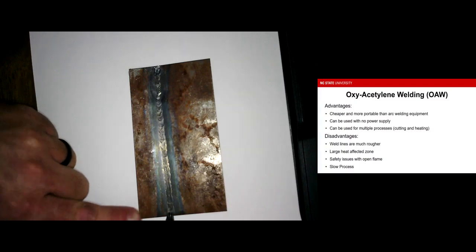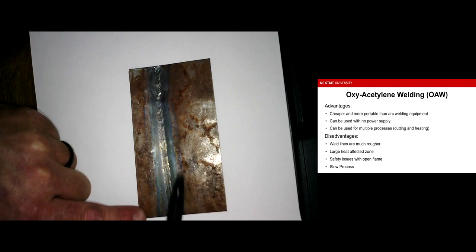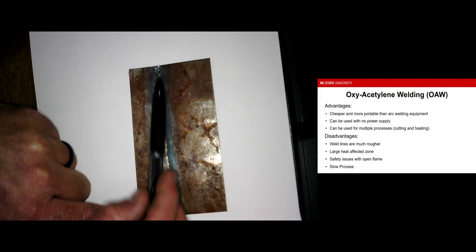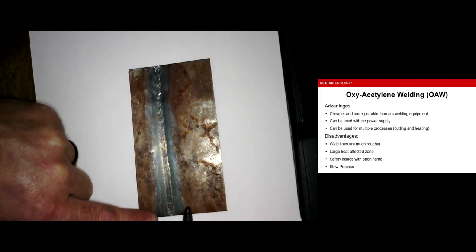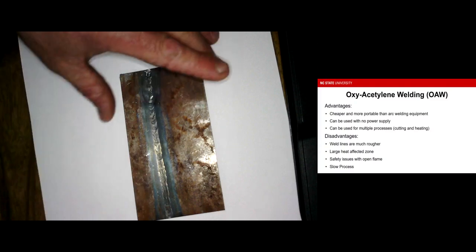The heat affected area, or heat affected zone as some folks may call it, is the area of the material that turns blue. It typically got a lot of secondary heating, which could affect the actual mechanical properties of that piece of material. It can make it more ductile or make it more brittle. It just depends on the type of material. And so trying to reduce that heat affected zone could be beneficial to the process. TIG welding has a much narrower heat affected zone. Oxyfuel welding is much more broad, and so that is a disadvantage.